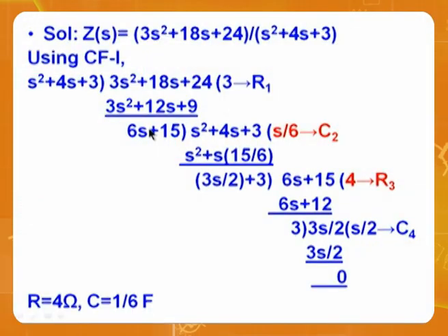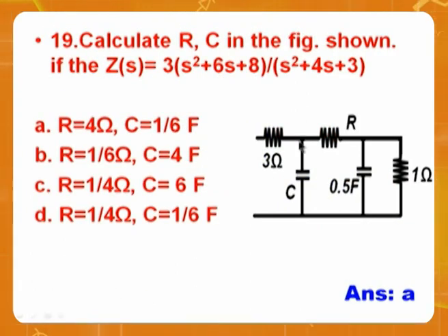Okay. Now take the function. Forget about the circuit. What he gave, you achieve a circuit. By achieving the circuit, you can identify the values there. You can simply say what should be the values of R and C. For this one, I can give you a guarantee, this is a ladder network. Therefore, whatever components are absent or values are not given, you can identify. So this is also one of the ways he is asking problems in network functions. That's why I titled this as not simply synthesis. It is also network functions.